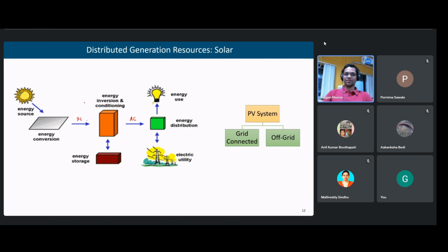And even for storing into the battery we need some control. Because sometimes there is also a DC converter inside, because the output voltage of the solar panel is low, so we want to boost it to a required voltage. For that we use either boost or buck boost converters. Now it is DC here, because it will go to battery storage. It will store.